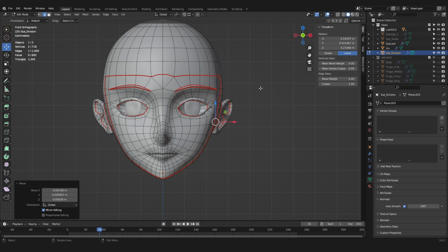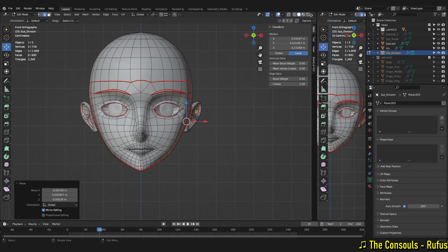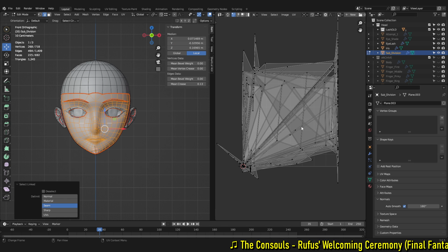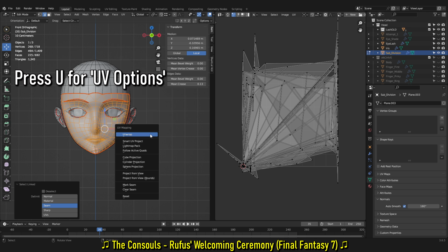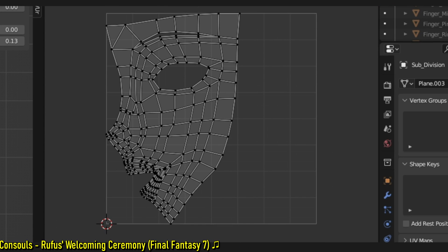By hovering over the corner like this, the cursor turns into a cross, allowing us to drag out a new window. In the top left corner, select UV Editor. With your cursor in the 3D viewport and your selection highlighted, pressing U will open the UV options. The most common way would be simply select Unwrap. This will create an island over in the UV Editor.